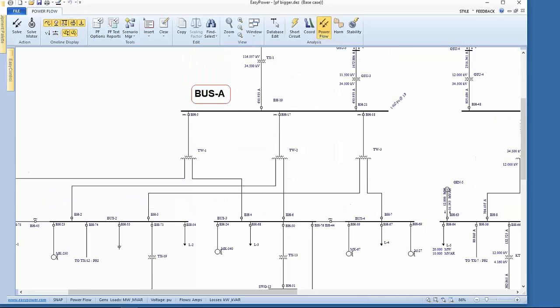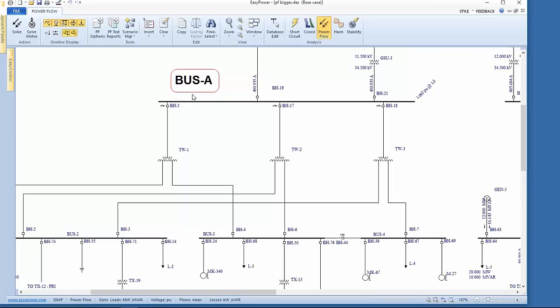You may have noticed when I started off that this breaker was open, and that's the error that I introduced in my system: with this breaker open, I have a fair amount of overload induced that's not necessarily part of my circuit. So again, because that was introduced artificially, I'm going to go ahead and close each of these breakers.